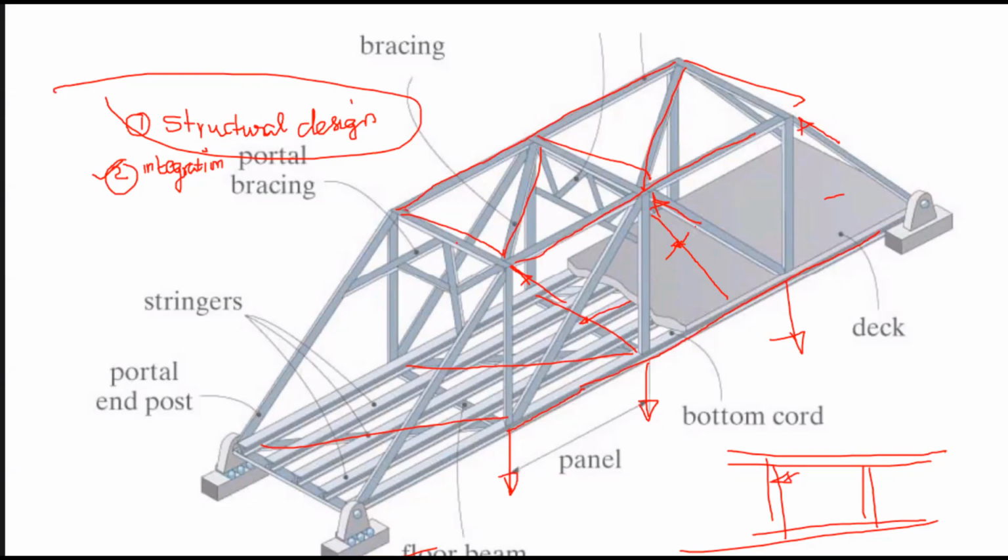So primarily the top girder is introduced as a wind girder. The horizontal forces flow through the trusses from one truss to the other, and in the wind load we can calculate shielding. Without shielding, that's a different thing.